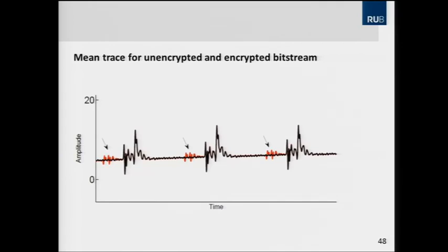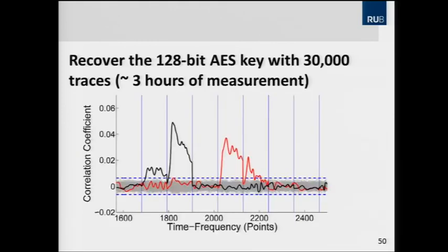Since I'm here with this, it was obviously successful, and here you can see a result of this. This is the approach of differential power analysis that I already explained, where you test small hypotheses for the key. Here in gray, you see 254 curves that relate to the wrong key candidates.